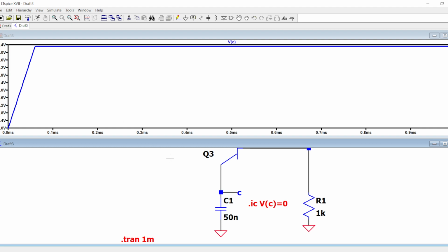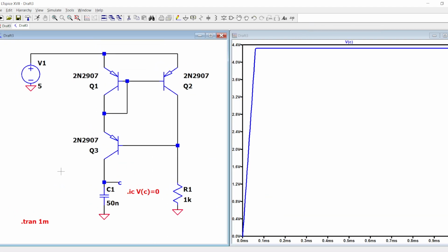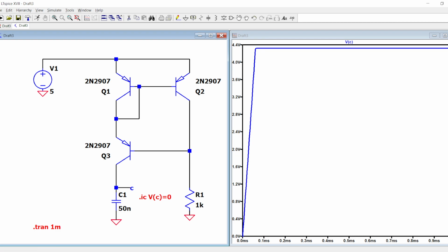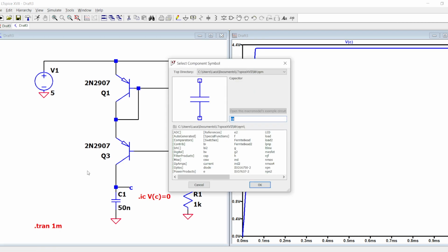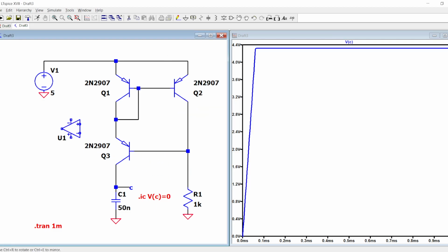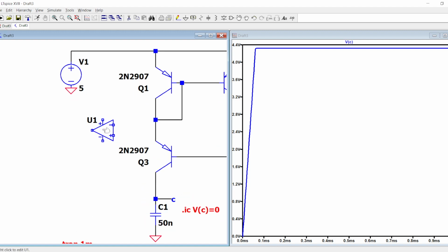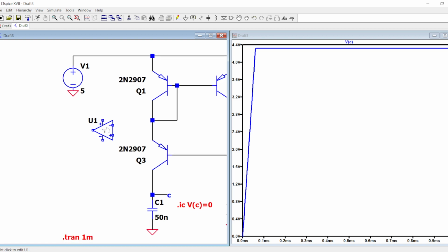Now we need to design the logic so that when it reaches a certain voltage, it will create a ramp. So we need to design a comparator, and we also need to imagine that this is inside an integrator. So it is an IC circuit. So we can only allow ourselves to use one op amp just because we want to make things faster.